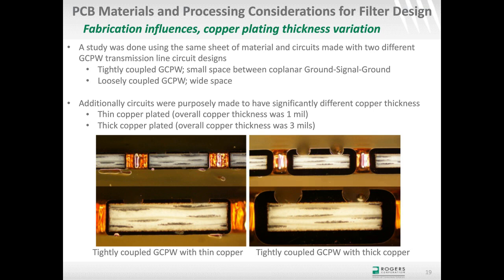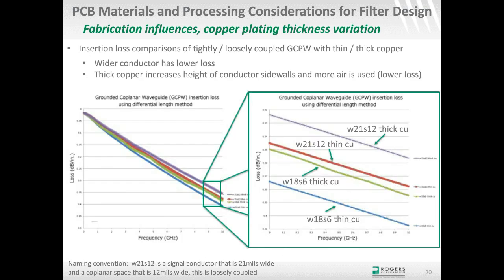I went off and did insertion loss testing, and this is a result of that. What I found was there's a pretty distinct difference in the RF performance. In this range of frequencies, by the way, I ensured that the return loss was very good. I had to have at least 15 dB or better return loss, and in reality, all of these were better than 17 or 18, so it's pretty good return loss.